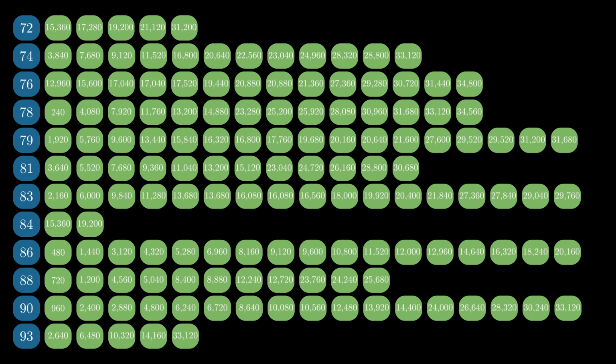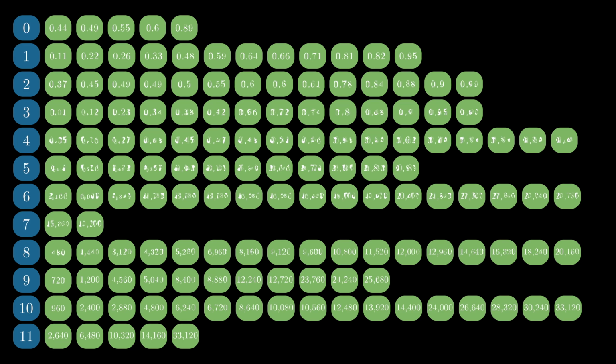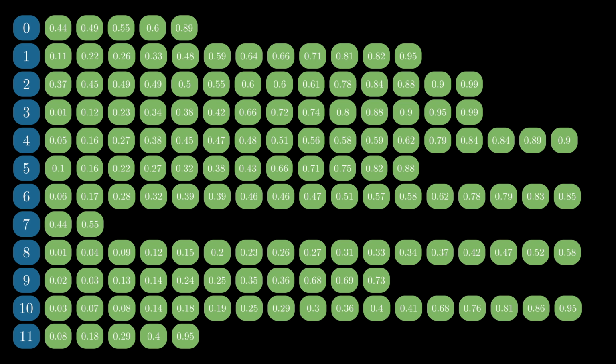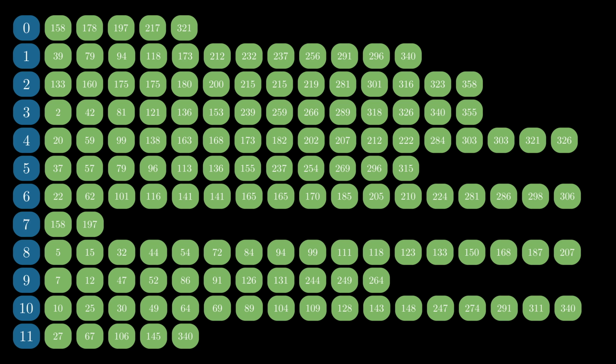We can form rows by listing every unique note that is played in the song. Then for each note, we can form columns that indicate every instance when that specific note should be played. For simplicity, we'll give each note a channel number from 0 to 11, each corresponding to one of our 12 cams. If we divide every time value in ticks by the length of the entire song, we can normalize each to be a value between 0 and 1, and then finally multiply by 360 degrees to scale it across the circular cams.